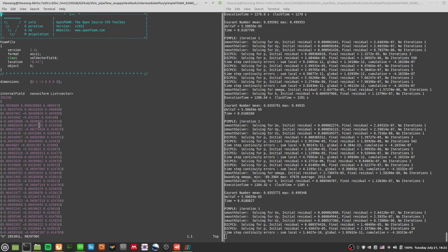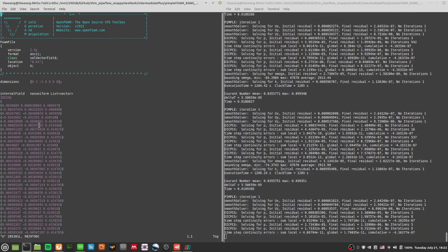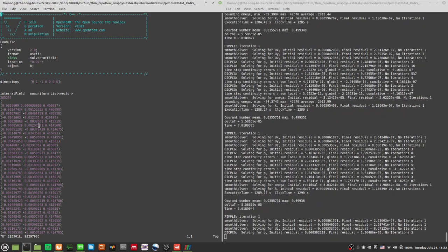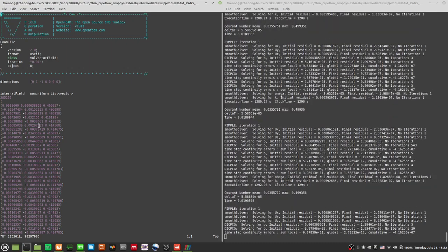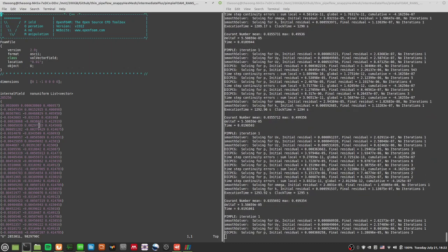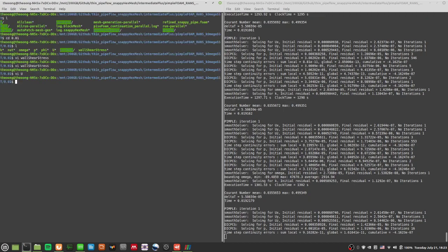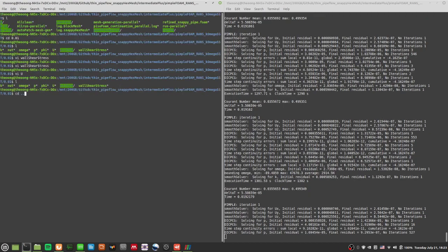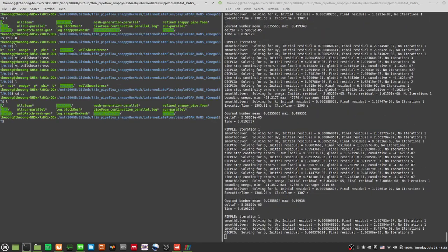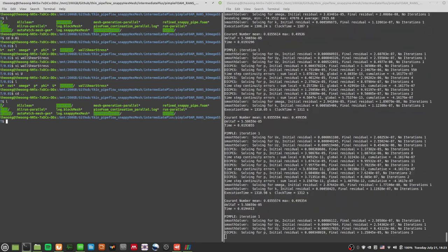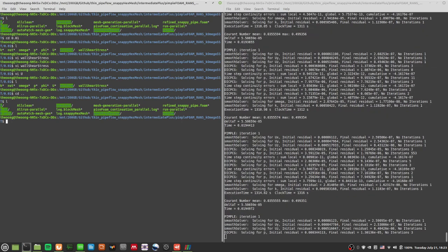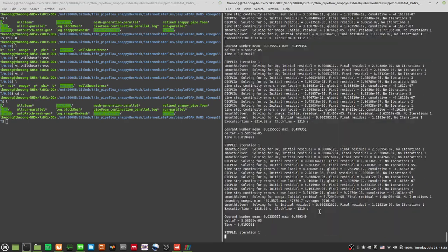Typically, the number of cells here is typical of a large eddy simulation. Usually 1 million cells is going to take a very, very long time to finish, so you might not want to make it so long. But anyway, it's just for demonstration purposes, just to get a flavor of what's going on, and it looks like the simulation's rather stable.